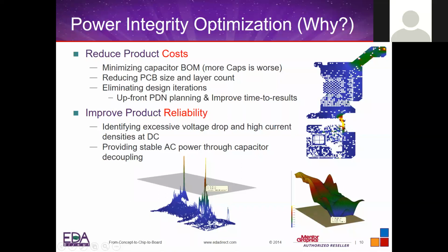You might think it's a software issue when you go back to the previous version of the system software, but it's actually a PI issue right here. And when you get this kind of problem, the board may be deployed in the field, and through an upgrade, it becomes intermittent. So it will cost a lot to retrofit and mitigate these problems. You have to send it out and swap them, send the field application engineer out to debug the issue. So it is better to contain and design the problem before it gets into the field. And that relates to reliability also.